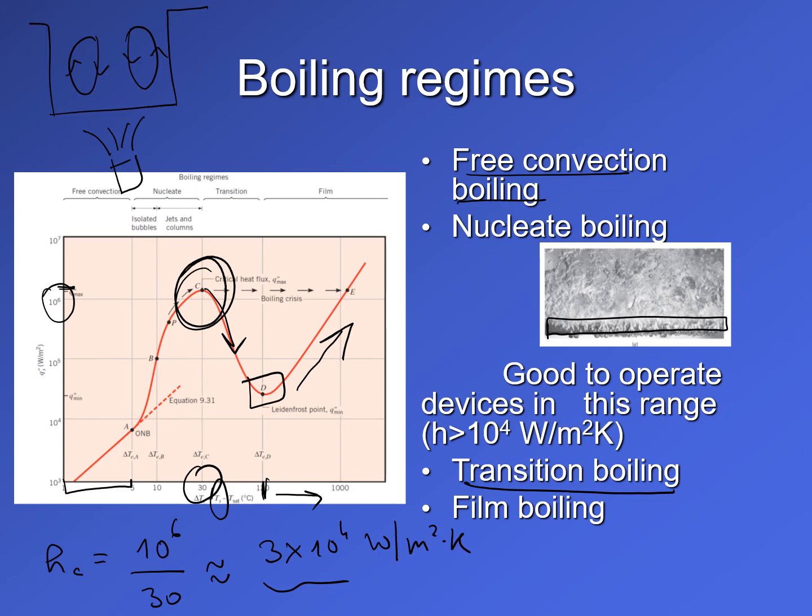So these nuclear rods become very hot. To increase the rate at which you lose energy from these nuclear rods, we use boiling heat transfer. So this phase change phenomenon results in very large heat transfer coefficients, which we can then use for cooling the system as quickly as possible.